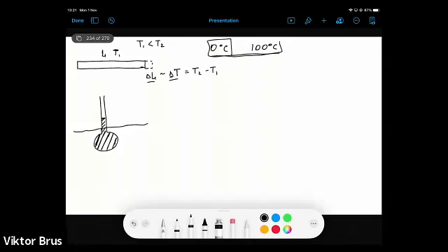If we don't reach this equilibrium, a part of the mercury on the outer sides of this volume will be at a higher temperature than the internal volume of mercury, and that will result in wrong readings of this thermometer.